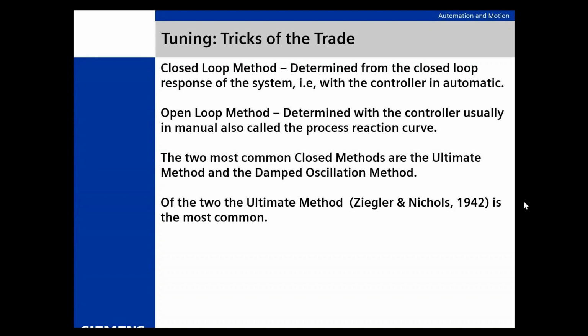Okay, that was the rage up until the microprocessor. Okay, that was kind of the place to start. Wasn't perfect, but it was a good place to start. Most people use the closed loop method. The open loop method, I don't use that too much because I don't like it. But the closed loop method, I've got my loop, and now everything supposedly is in this loop. I've got my measurement, and I've got my final control element, and I'm going to auto tune if I can. Okay, or I'm going to try to auto tune this.